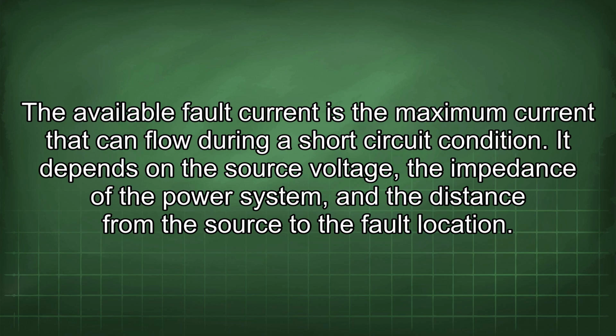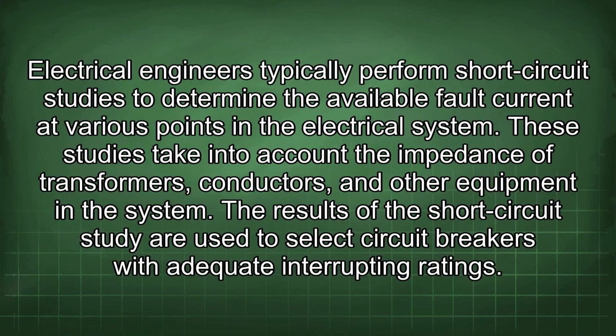It depends on the source voltage, the impedance of the power system, and the distance from the source to the fault location. Electrical engineers typically perform short circuit studies to determine the available fault current at various points in the electrical system. These studies take into account the impedance of transformers, conductors, and other equipment in the system. The results of the short circuit study are used to select circuit breakers with adequate interrupting ratings.